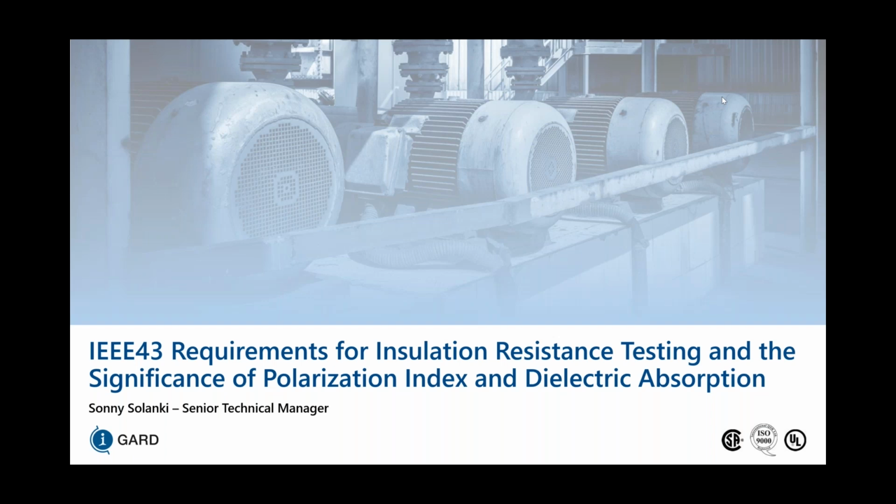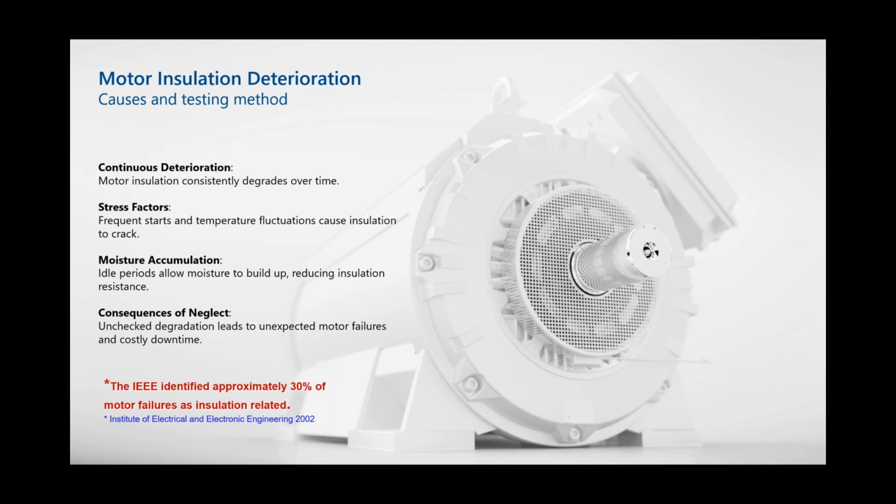Today's presentation is on IEEE 43 requirements for insulation resistance testing and the significance of polarization index and dielectric absorption. There are many ways a motor can deteriorate over a period of time. Motors typically degrade due to wear and tear. There can also be stress factors, such as frequent starts and temperature fluctuations, that can cause insulation to crack. In addition, in a very high moisture area, idle periods allow moisture to build up, reducing insulation resistance. If unchecked, degradation leads to unexpected motor failures and costly downtime.